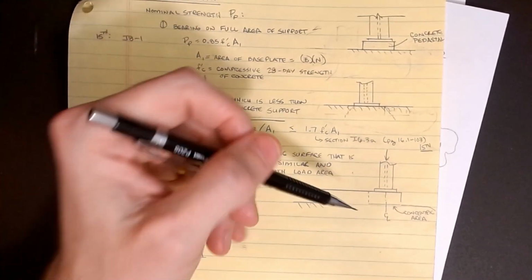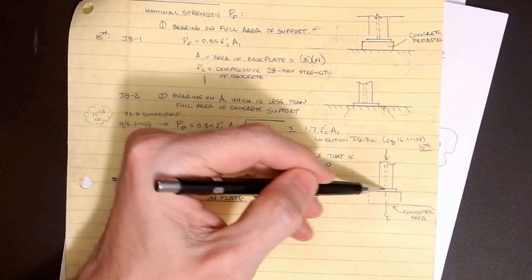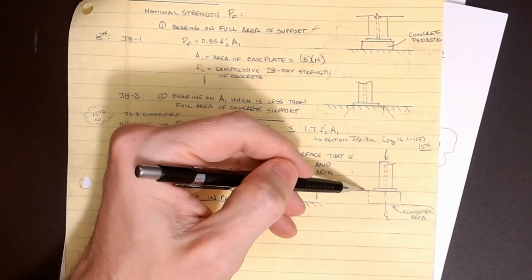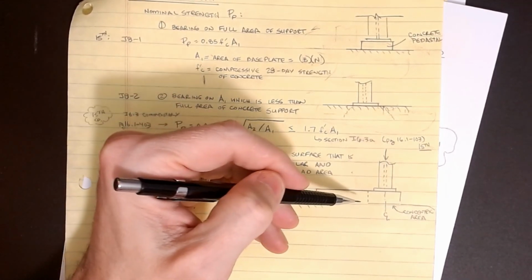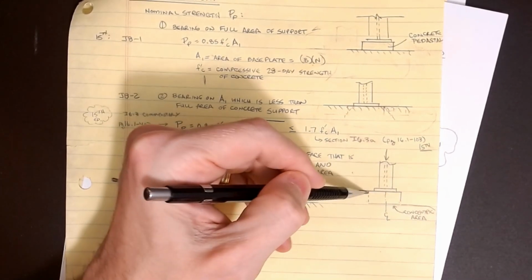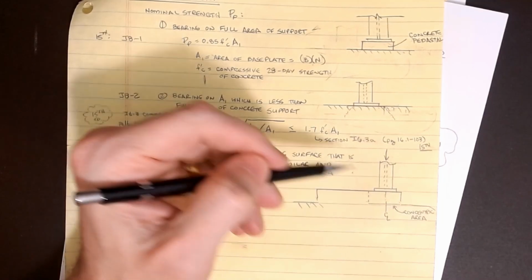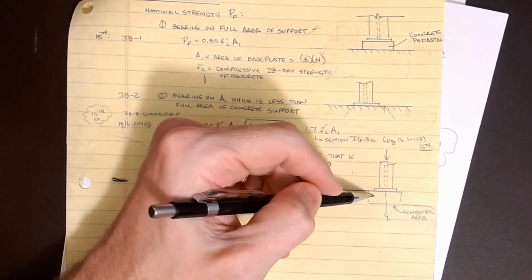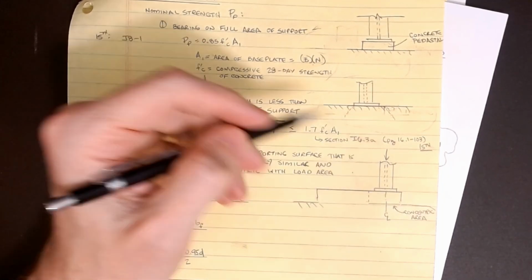Okay, so if I look at this from the side, we can see that if I put a plate that is close to one edge, all of the material on the slab over here does nothing to help with the load. We have to consider that I take this dimension and I double it, and that becomes the width of the concentric area. The center line of the column has to line up with the center of this area, and this is the area that's responsible for resisting the stress.